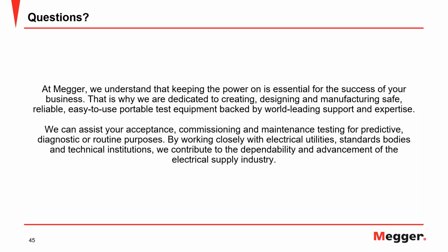But of course, one of the things that we can look at is not only power factor. Dielectric response per se is a tool that will allow you to look into capacitance and dissipation factor or power factor. Personally, I like to look more at the capacitance changes during, for example, a dryout process on power transformers. So I always look into my dielectric frequency response of the capacitance rather than the tan delta.